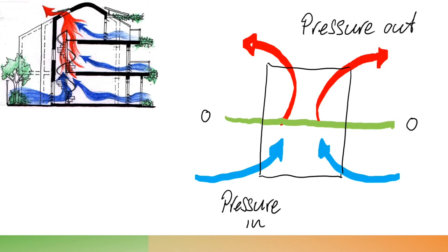If we're getting too much cold pressure coming in, that's going to push the warm air out a lot quicker. So the building's going to cool rapidly. It's not going to be the best in terms of human comfort. Whereas if we don't have too much cold air coming in, as the hot air goes out, it creates a vacuum and it'll suck it through.